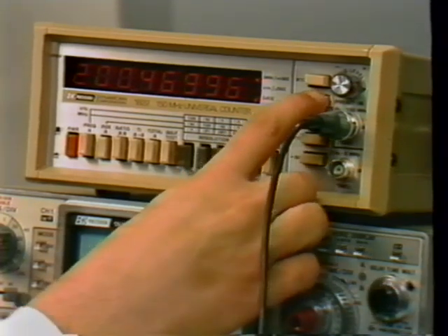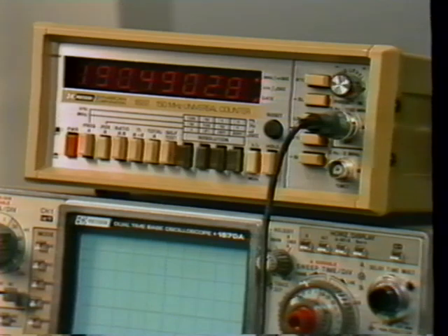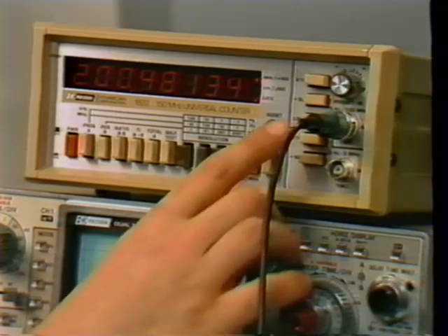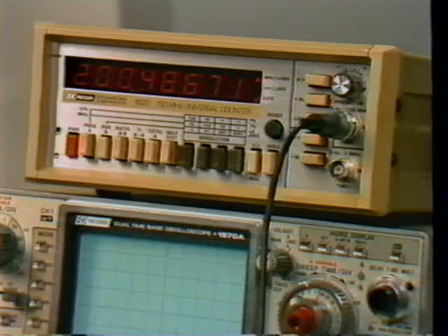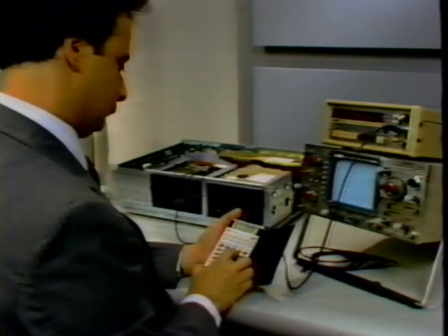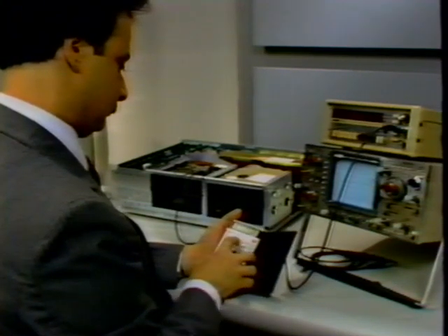Next, select the trigger slope. Since the index pulse is low going, use negative trigger. This drive speed is specified at 300 RPM, which converts to a frequency of 5 Hz. Engage the low-pass filter switch to eliminate the possibility of triggering on high-frequency noise. If we convert 5 Hz to period, we arrive at a figure of 200 milliseconds.